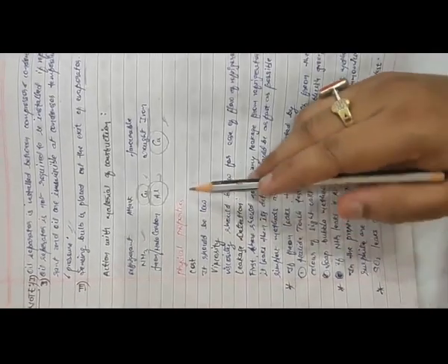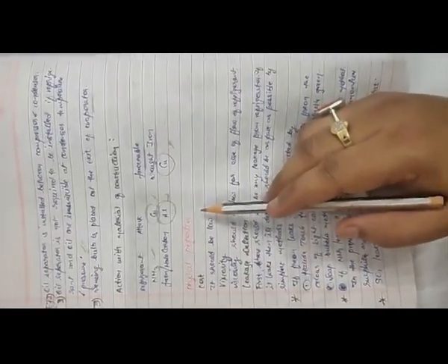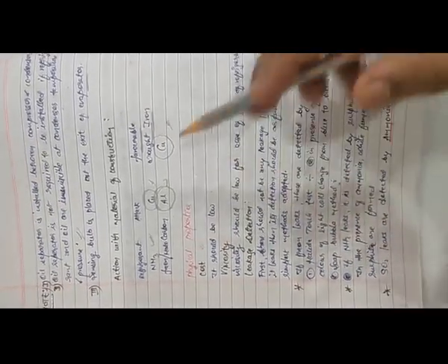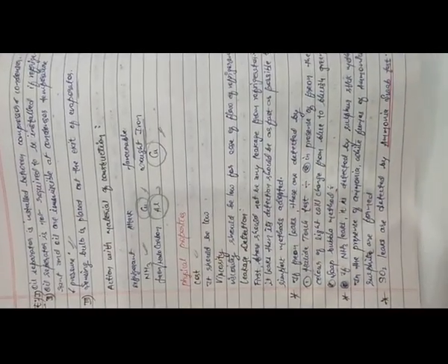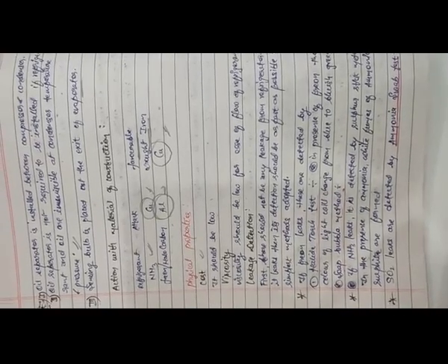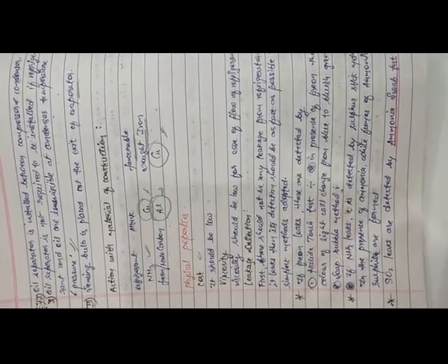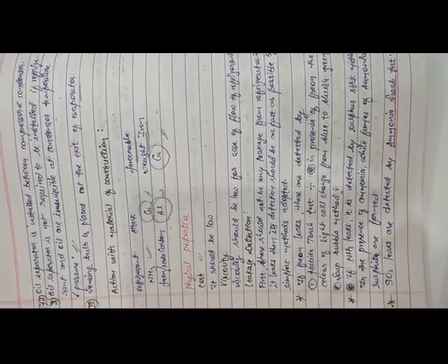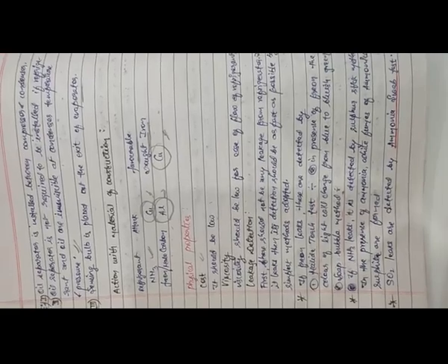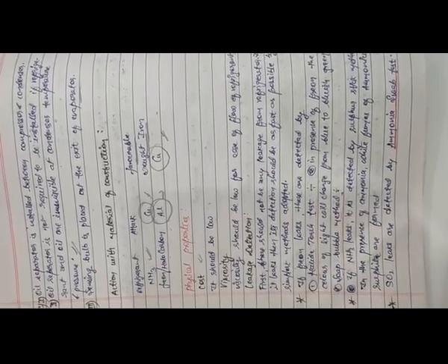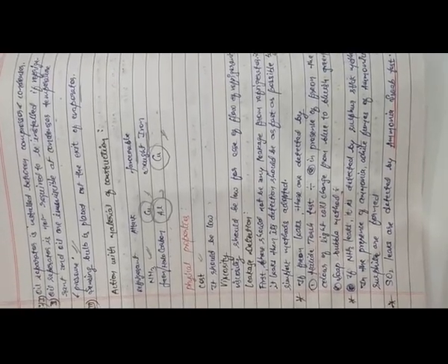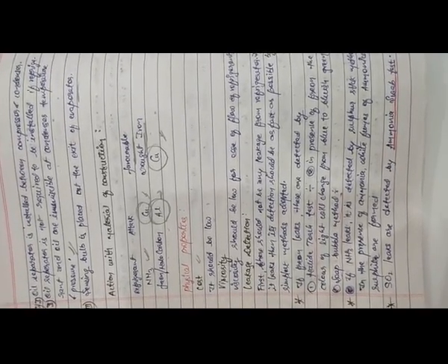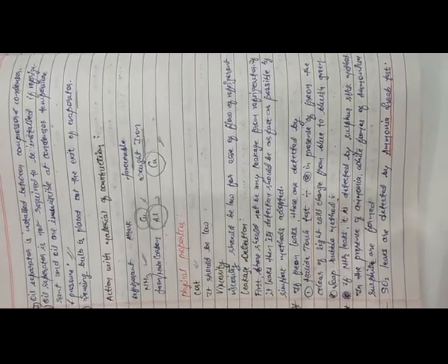Now we'll go with the physical properties. The physical property is mainly cost. It should be low, as we all need any refrigeration system to be economical, and any refrigerant that is being used should be low cost. Otherwise it will be very difficult to use it at every location or every application. Viscosity should be low for ease of flow of the refrigerant.